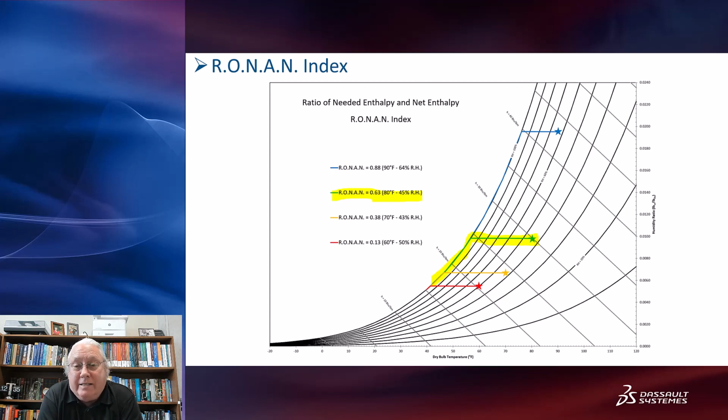So the idea is that if you start like in this blue one up here, the percentage of the energy you're putting in to get to the dew point, 100% relative humidity, is much less than the total amount of energy you're spending to get actual water.